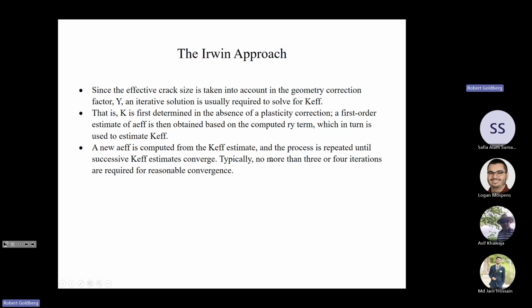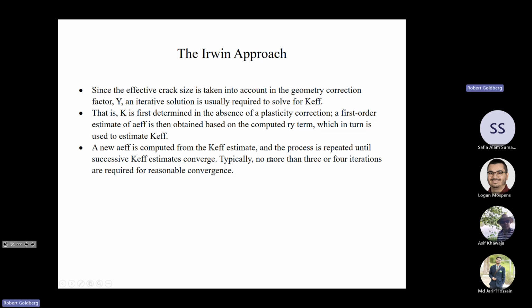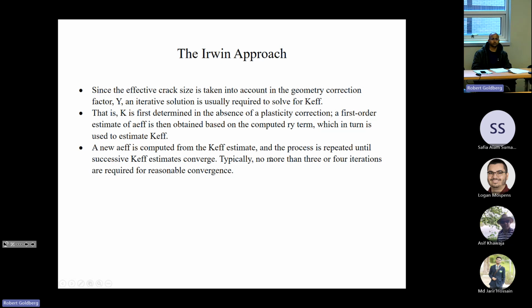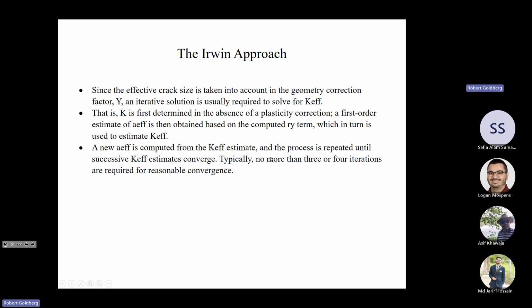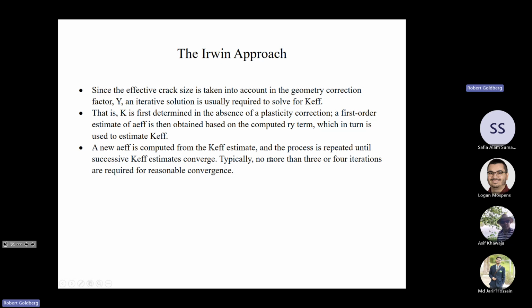And since the effective crack size is taken into account in the geometry correction factor, in the general case, when you apply this method, you generally need to use an iterative solution. First, you compute your stress intensity factor without any plasticity correction, based on your original crack size.